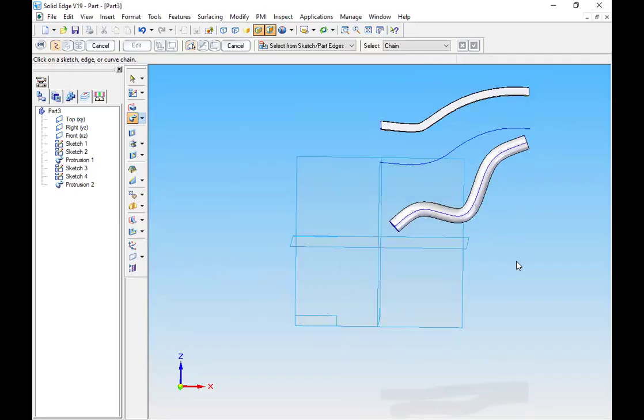So the two profiles should be perpendicular to each other. If you take up a profile plane or top plane, then you can take a front plane as another plane. So consider any two planes which are perpendicular to each other. In one plane the profile, in another plane the path. That should be maintained for swept protrusion. The profile may be anything.